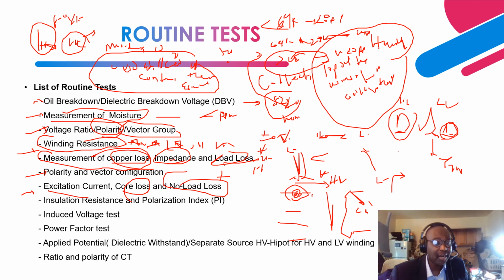So the excitation current test is performed to determine defects, damage, or failure of the core of the transformer. Right, the laminations, right? If there is lamination insulation degradation, which basically results in defects, the excitation current is going to show you. It also manifests broken strands and turn to turn shorts, right? If you have that condition, it's going to show in your excitation current.